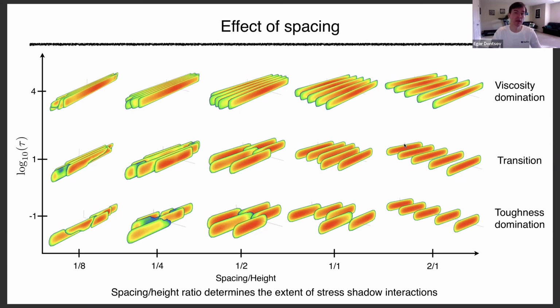So basically what I did is put relatively high perforation friction, and then I checked after the fact that the fluid is more or less, to within a few percent, uniform. And again, you can play with non-uniform, and I did it at some point, but it's an additional parameter. And once you start having more and more parameters, it's really easy to get lost in all this parameter space.